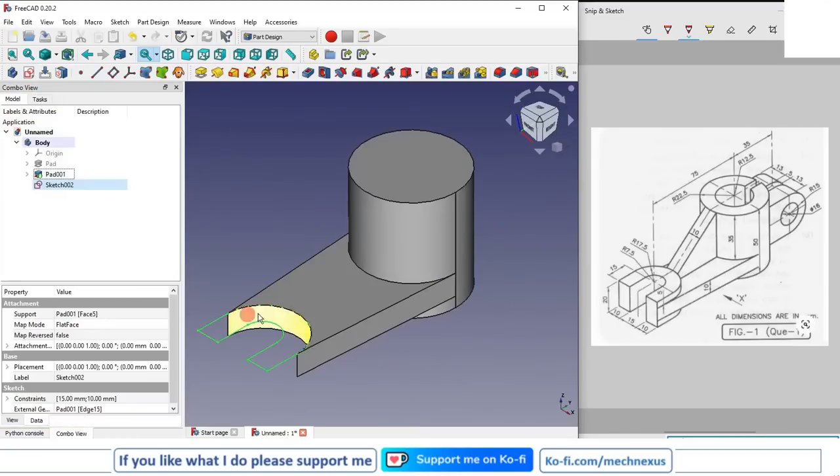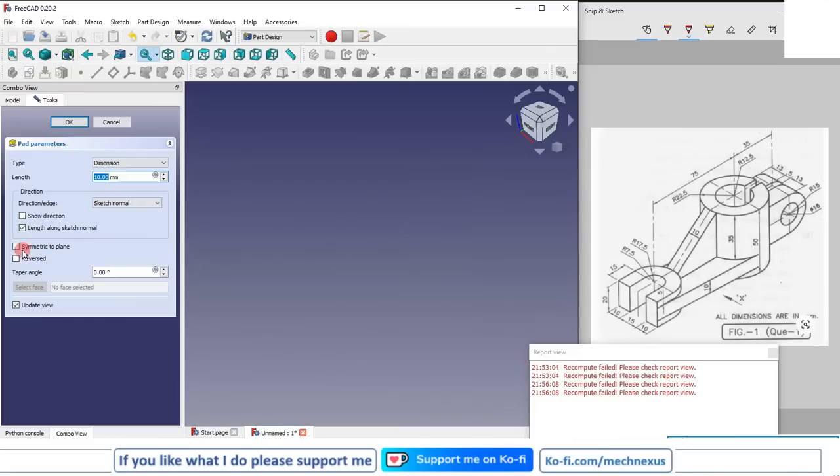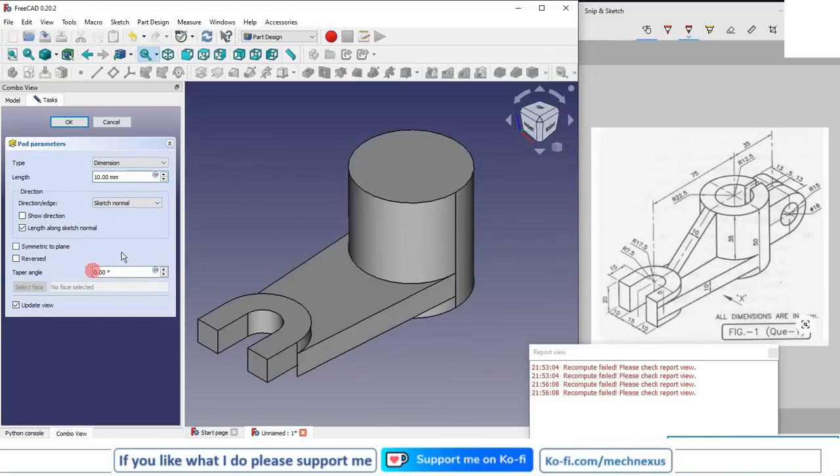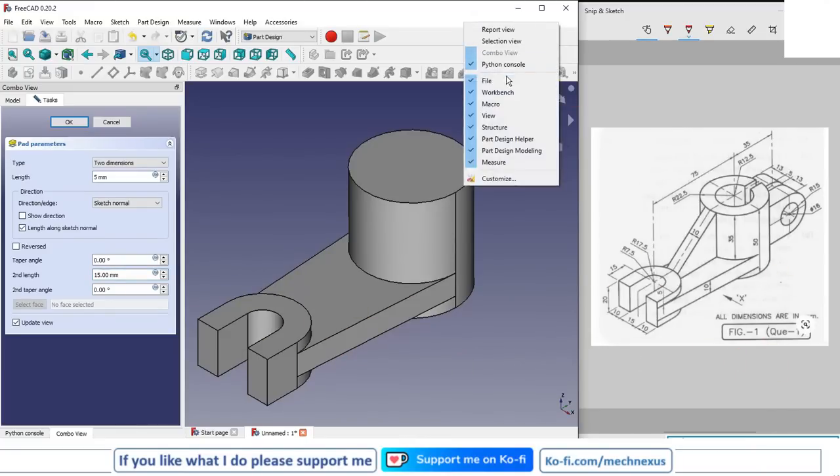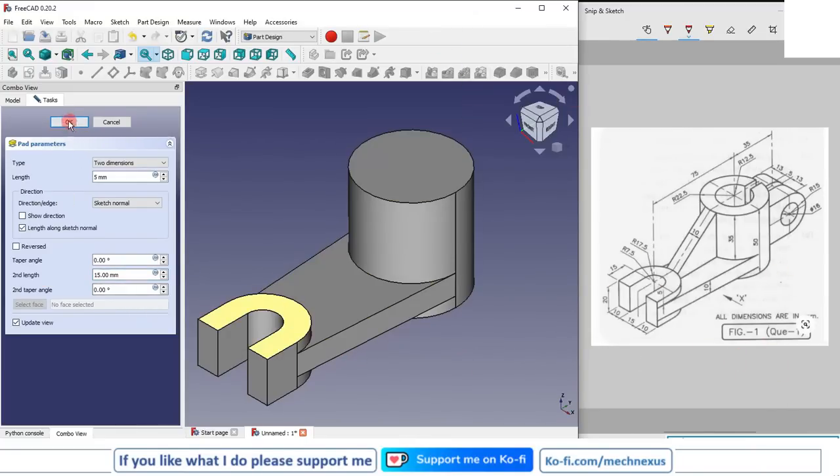Now I will close it, and in one direction it is 5 mm and in the other direction it would be 15 mm. So I will select the pad, click on two dimensions, so on one side it will be 5 and on the other side it will be 15. Right, now I will close my report view. Okay,